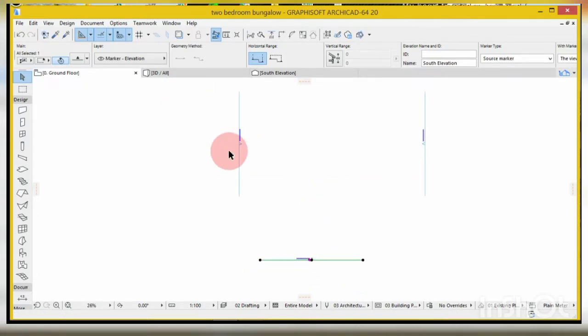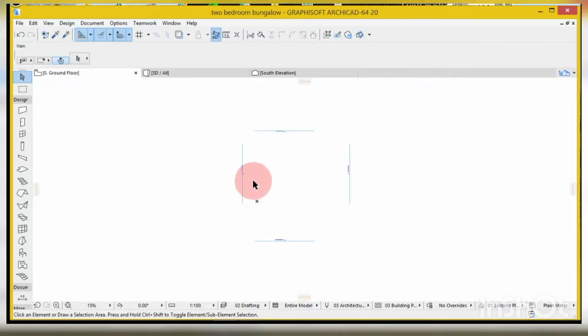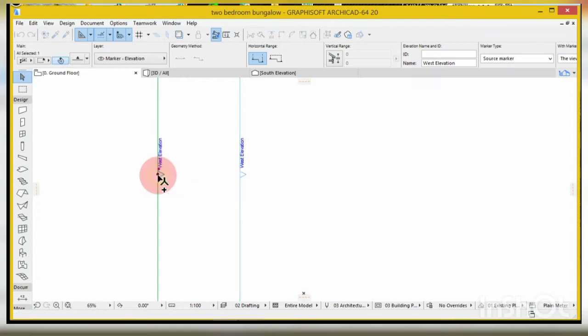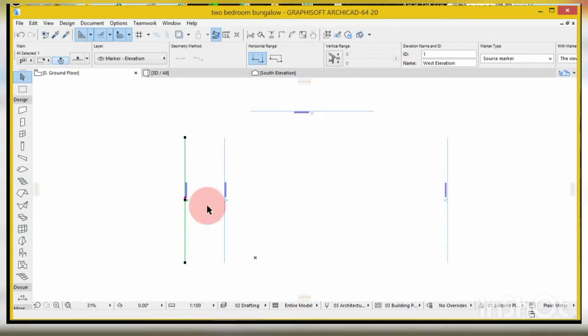Just as you work with it, you learn more of it. The shortcut of dragging: you hold your shift to select, then you hold your control shift and press D on your keyboard. That is control shift D. Okay, sorry, control shift D. What I just did was duplicate.